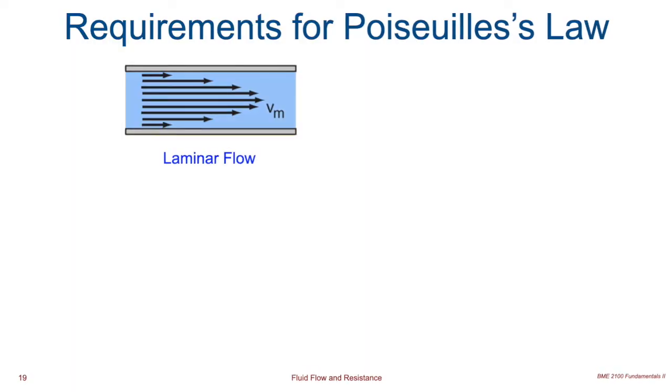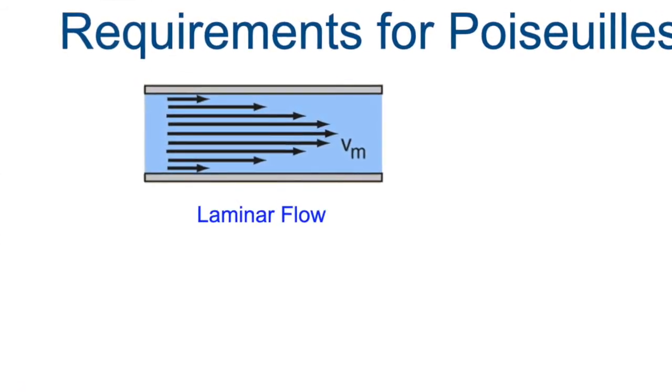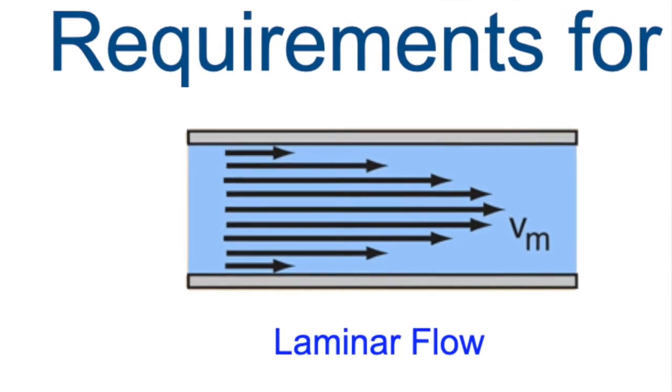Now another thing that we're going to have now explicitly for the first time is something that also belongs to every equation. Every time we write down an equation, and we have to be concerned about this as engineers, we have conditions under which that equation holds, or assumptions that are built into that equation. These assumptions show up in the math when you derive an equation carefully with mathematics. They also show up in the kind of assumptions that went into this discussion we just had about what determines flow. For example, we assumed we had laminar flow. That's an assumption. There's a thing, as you know, called turbulent flow that's non-laminar, and that's going to change things. So the relationships that we have described by Poiseuille's law will hold under the condition of laminar flow. It's one of the working assumptions, one of the constraints.